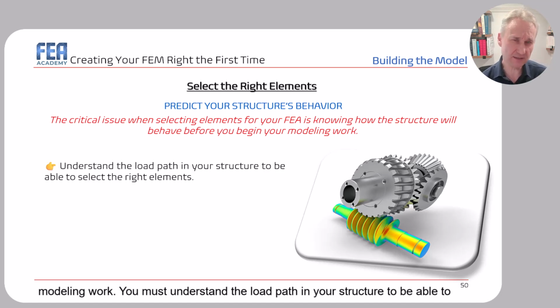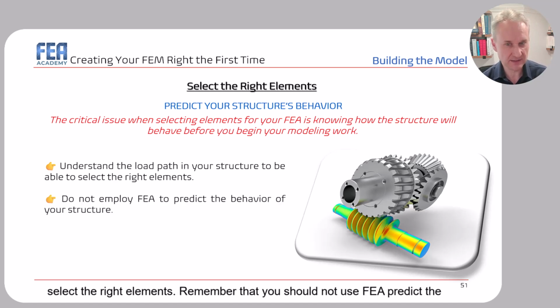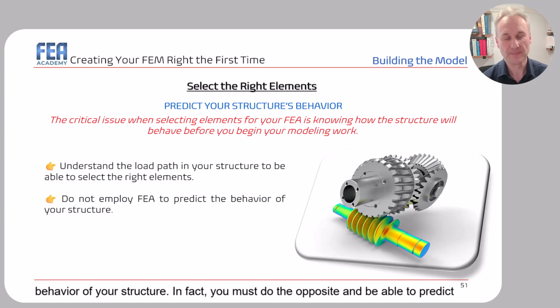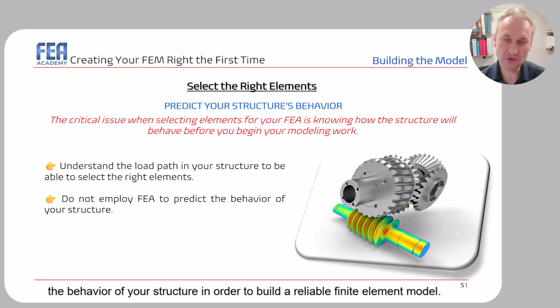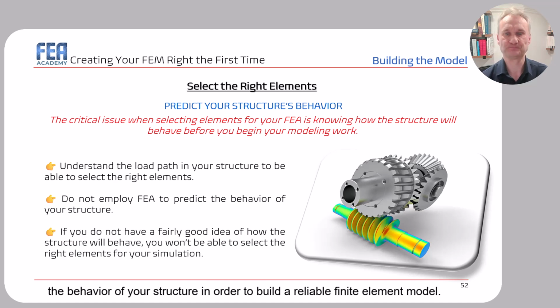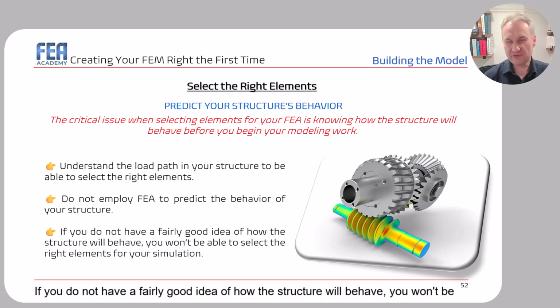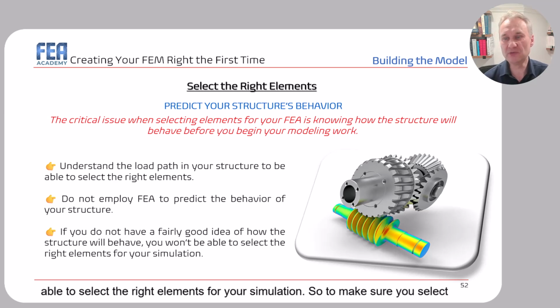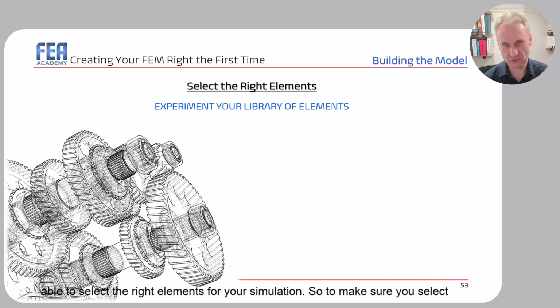You must understand the load path in your structure to be able to select the right elements. Remember that you should not use FEA to predict the behavior of your structure. In fact, you must do the opposite and be able to predict the behavior of your structure in order to build a reliable finite element model. If you do not have a fairly good idea of how the structure will behave, you won't be able to select the right elements for your simulation.